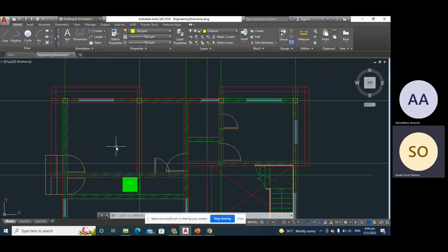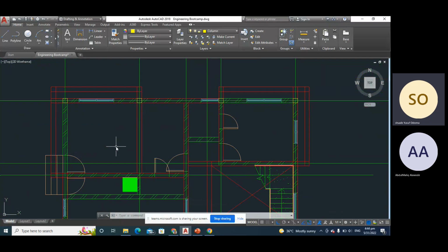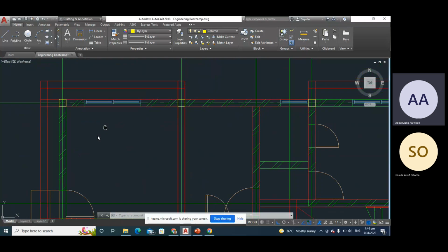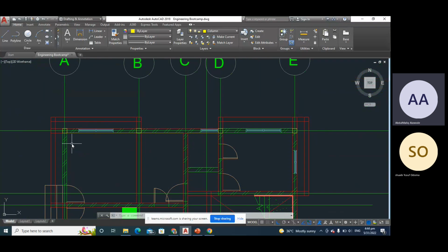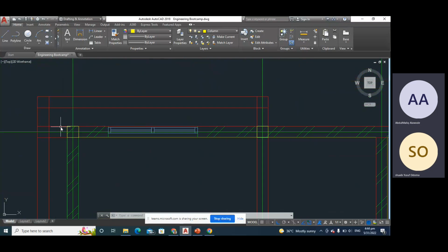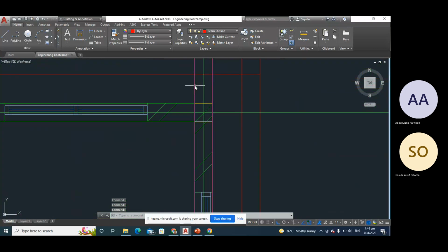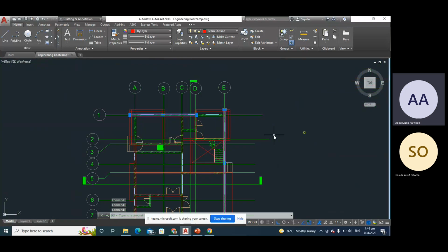I understand, but sorry, if you establish pillars at the cantilever point, they are more like a prop, and the pillars extend from the ground to either the beam or the slab directly. Is that not going to be more of a simply supported situation? What I've done now, my columns are not going to the slab, they are going to the beam, because yes, we have a beam here. We have a beam here too. Have you seen the beams?